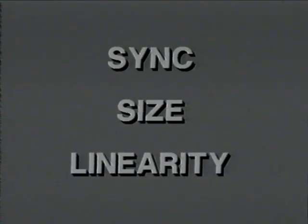Perform the vertical adjustments in the same order as the horizontal: sync, size, and then linearity. Once again, we first set the frequency, then the duty cycle, and finally touch it up with the linearity control.